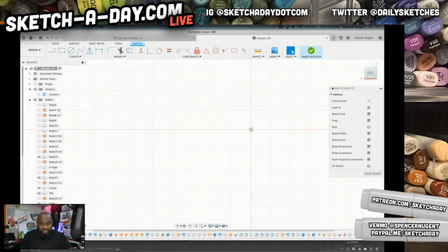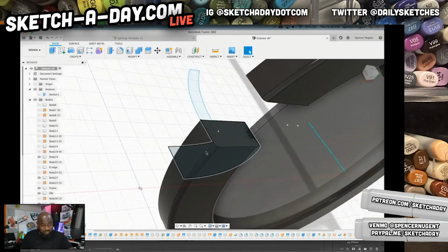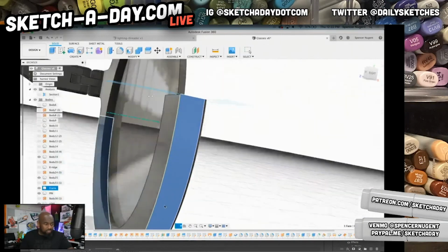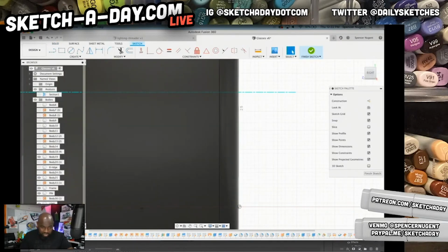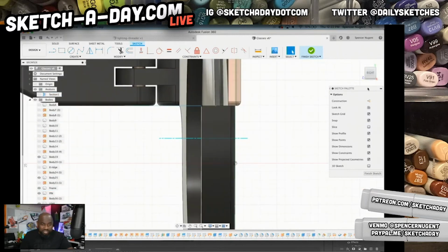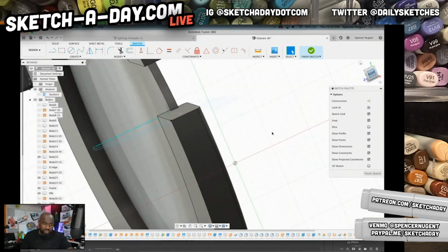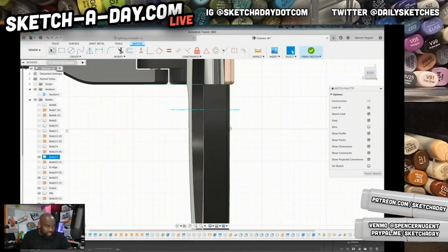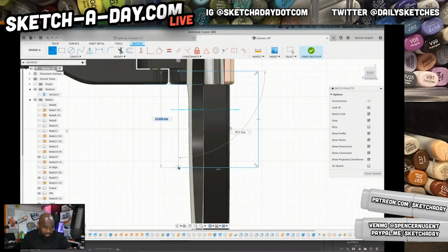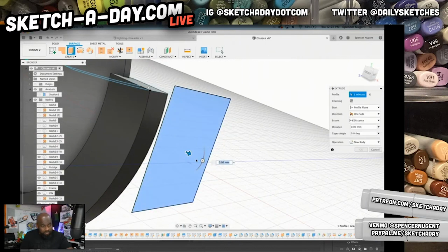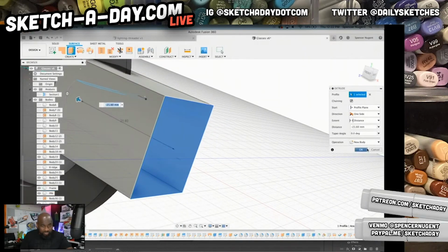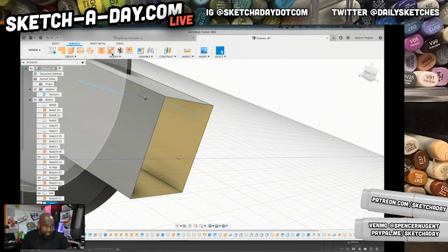So I think what I may have to do here, guys, is actually split the frame. Create a sketch on this plane. All these sketches are junk, so I'll have to get rid of those. But if I create a sketch on this plane, yep, now I can just pick the height that I want to split this thing. And since I don't want to split all the way through the model, I'm going to try and just draw a surface like this, a rectangle. Pick this profile. It's going to give me a surface like so. Hit OK, and now I can hit Split.